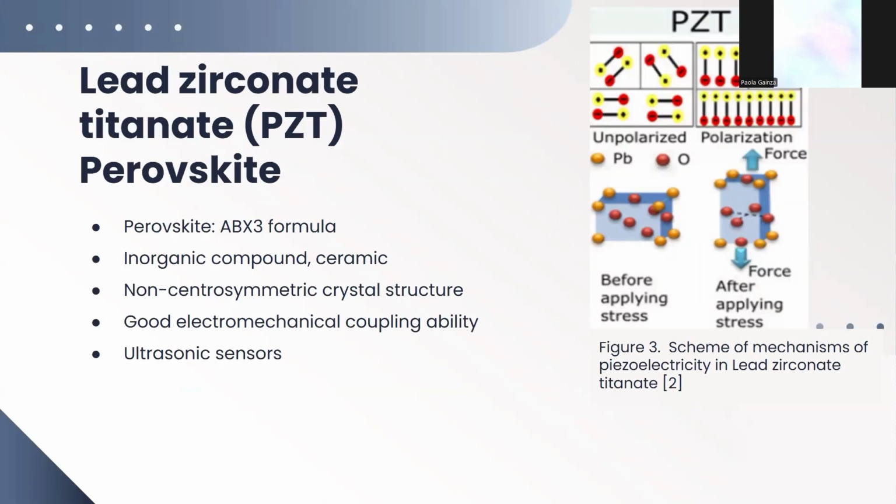I'll be talking about the specific piezoelectric materials on the same crystal structure that is perovskite. The perovskite structure is a specific crystal lattice with a general ABX3 formula, where a large A cation occupies corners. The smaller B cations are centered within the octahedra of X anions.